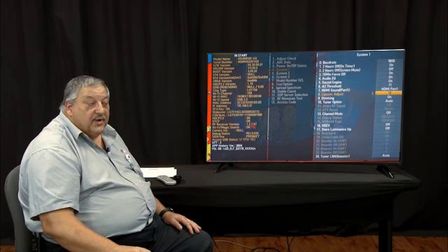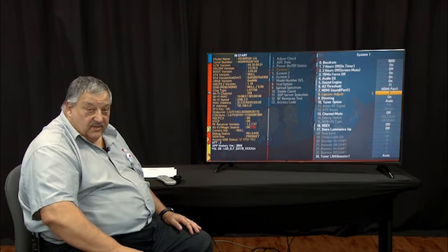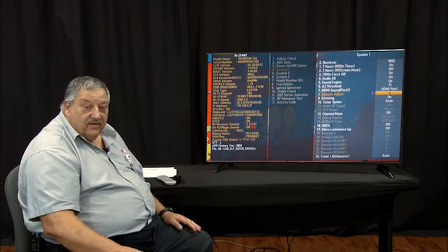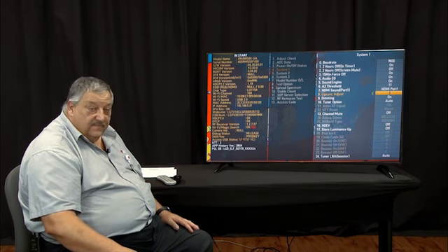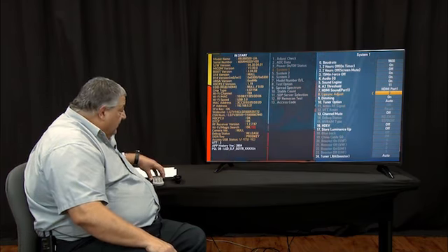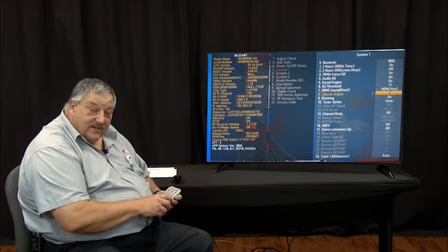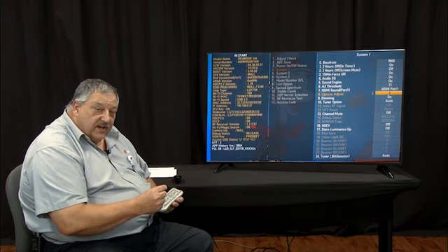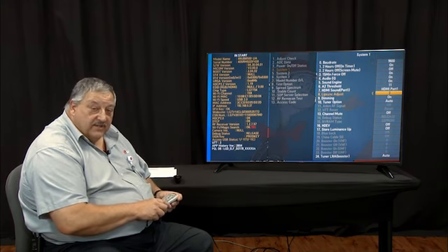So if something corrects the problem and they move to a new signal source, they're still going to have that delay, whatever you set up or advance from this menu. That's the only reason I would say use the customer's AV sync as a first step, because that will usually take care of the problem before you make this kind of an adjustment.